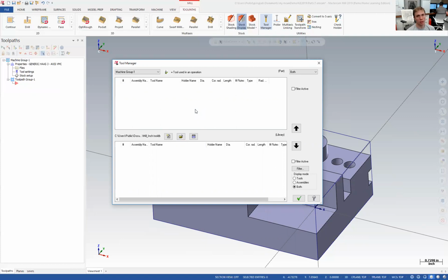If I run into a problem with my setup 4 hours into a cam, I have to scrap the whole thing and start over. Whereas if I do it mentally now, I've only worked on the part for maybe 5 or 10 minutes, and starting over is not nearly as painful. So while it's not critical, you can introduce tools as you create toolpaths and as you need them. It is still very helpful to try to do as much as you can up front.